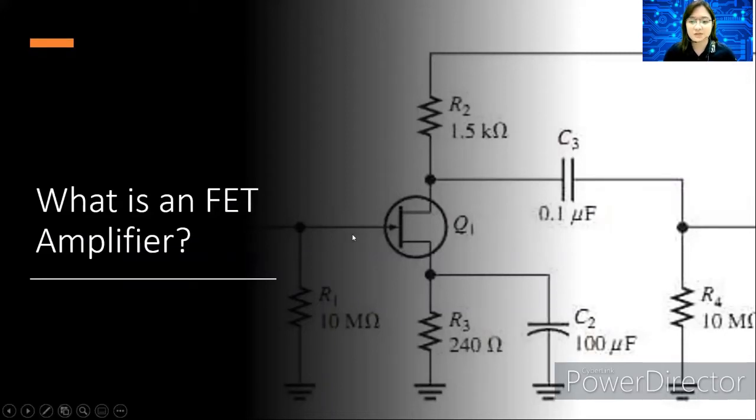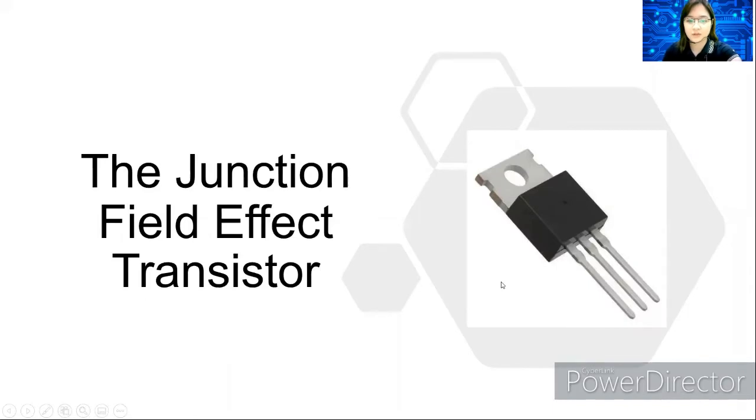By appearance, JFET and bipolar transistors are very similar. However, BJT is a current control device, and JFET is controlled by an input voltage. So the function of a junction field effect transistor depends upon the flow of majority carriers, electrons or holes only. So basically, JFET consists of an N-type or P-type silicon bar containing PN junctions at the sides.